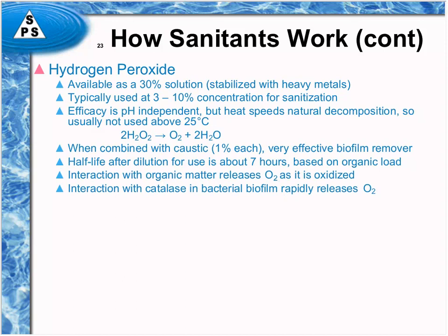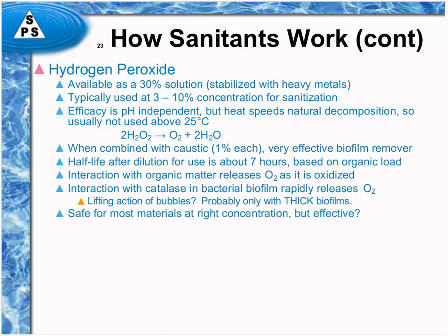And catalase that is present in all living, aerobic, growing matter will also rapidly catalyze the hydrogen peroxide to oxygen gas. Usually the concentrations you're using are so high that they will overwhelm the catalase mechanisms of neutralizing it that bacteria have. There might be some lifting action from the bubbles that form, but that's usually only when there's really thick biofilm present. It's safe for most materials at the right concentration, but for instance, at ROs, you can use it in ROs, but the concentration that is safe is so low that it might not be effective.